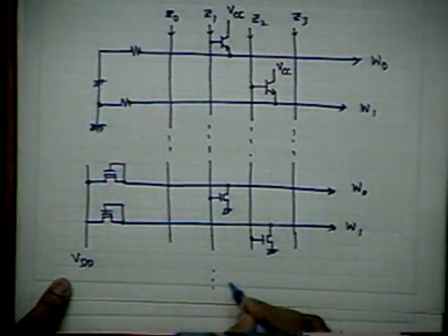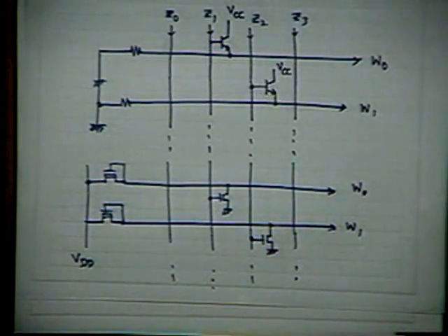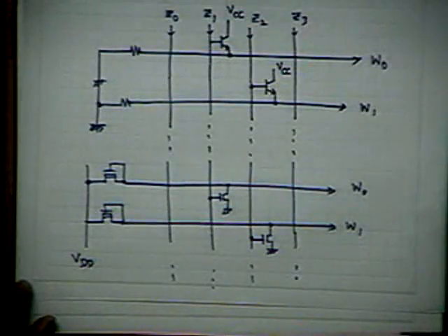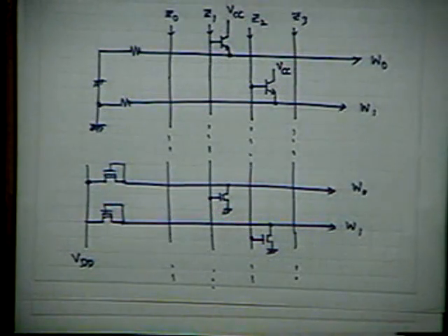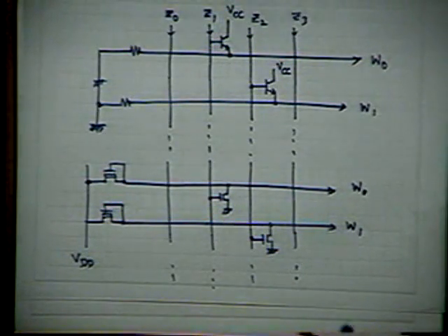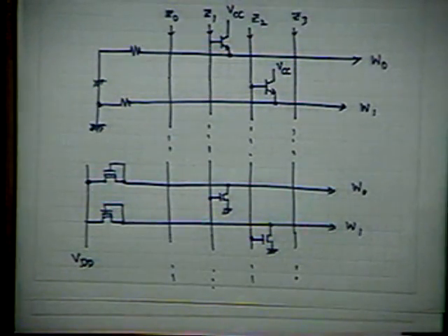And therefore, this so-called NMOS ROM is nothing but equivalent to the AND plane of a standard PLA. At each node there is a MOSFET, and you just connect or do not connect. That is up to you.